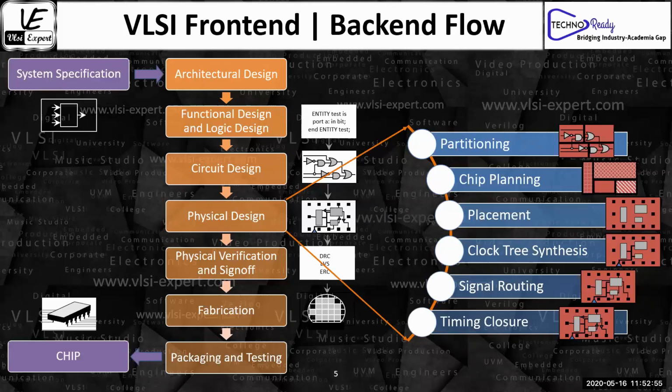And the timing closure. Remember, it is written here as closure. I'm not saying timing is something we do only at this particular stage. A lot of people think this is something we have to do at the end of the whole physical design. That's not the case, that's sign-off timing. But as such, we are going to do timing at each and every stage.